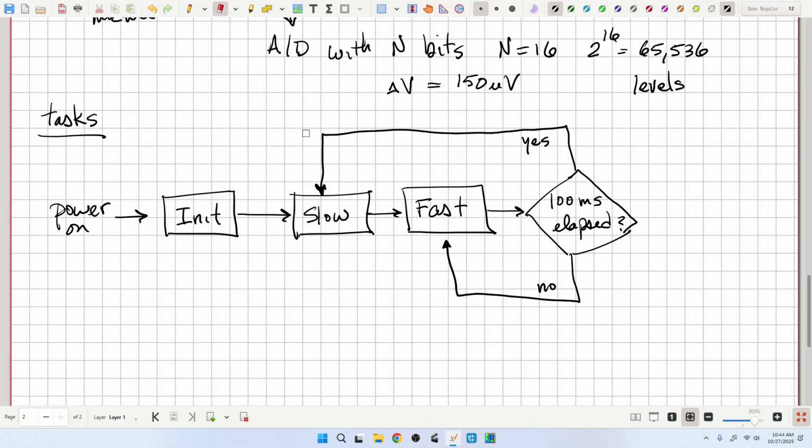And usually, at least the fast task repetition time can be set in the program. So in this course, we'll put essentially all of our programming into the fast task, other than some initialization steps we need to do. Now, in some PLC implementations, there might be other tasks, like a background task that's even slower than the slow task or what have you. But these are the basic ones that you'll see.